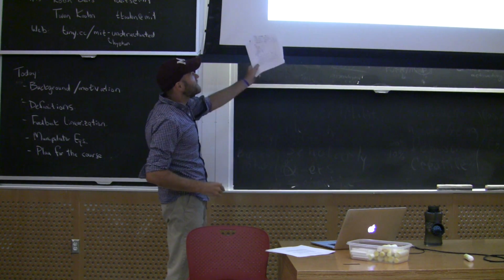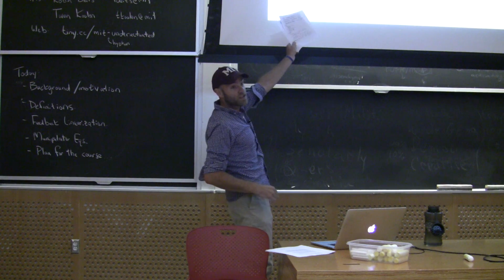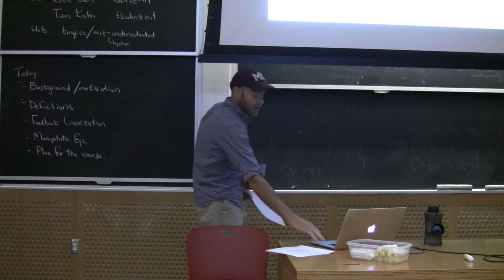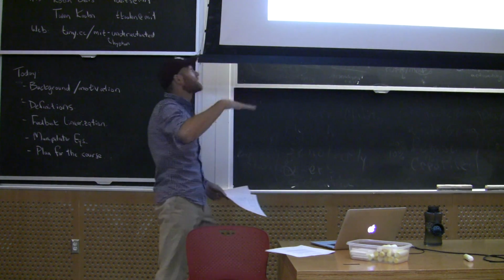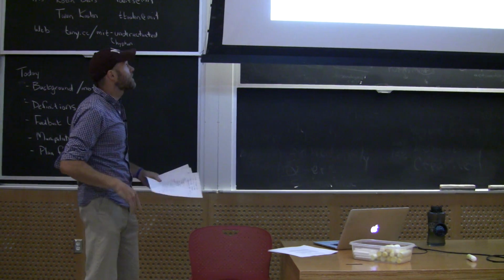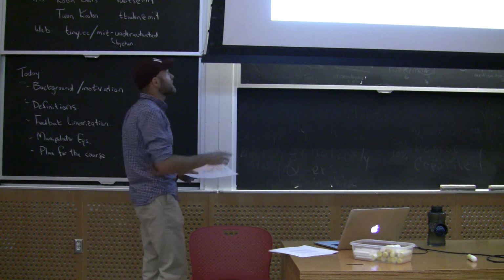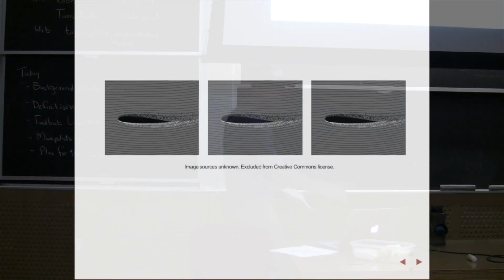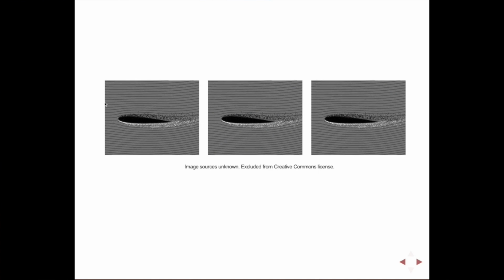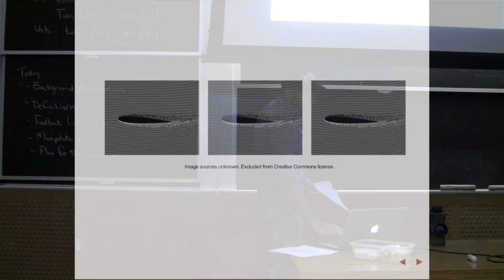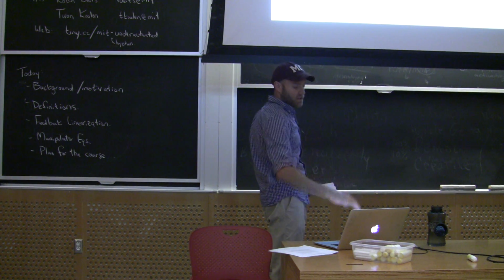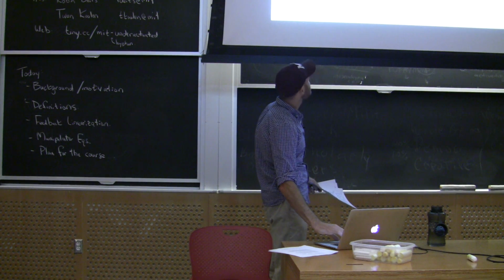So the reason that we do this in the control is because when your aircraft is at a low angle of attack relative to the flow, then we have good piecewise linear models of the aerodynamics. So this is a wing with these lines being the streamlines. And when the aircraft is in line with the direction it's moving, then the air moves nicely around the wing. If I bring my angle up to a small angle of attack, again, it stays connected to the wing.